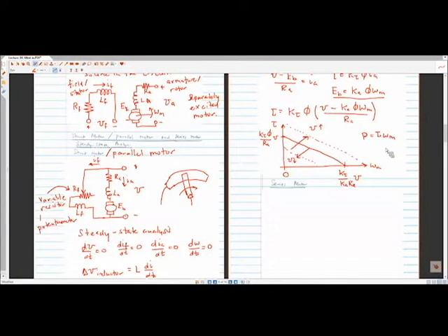We'd have to analyze this a bit more, but torque already has omega m in it, and now we're multiplying by omega m, and it also has a term that doesn't have omega m. So it's going to be one term that is quadratic and another that's linear. We'd have to take the derivative with respect to omega m to figure out what point that is.